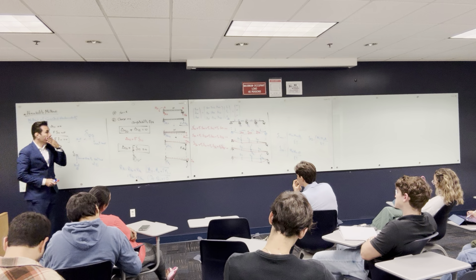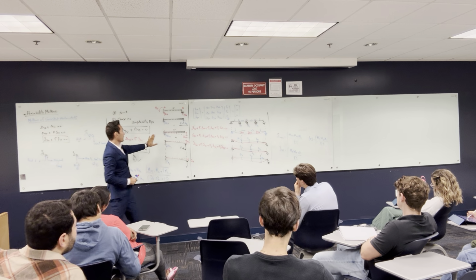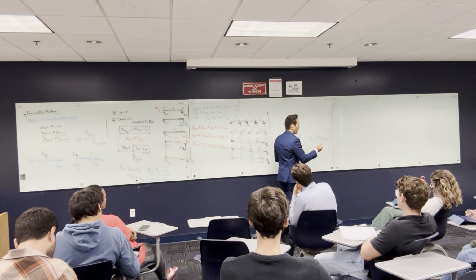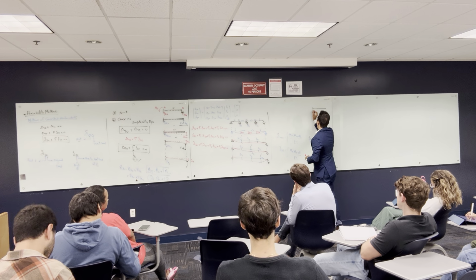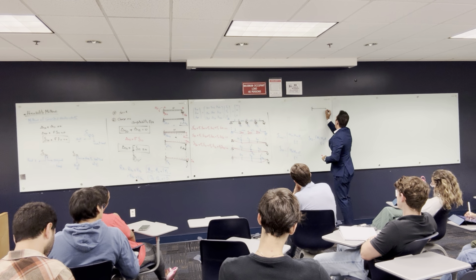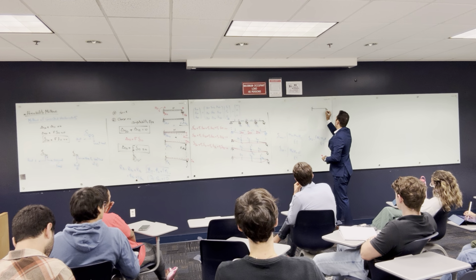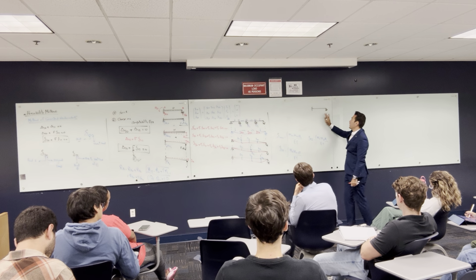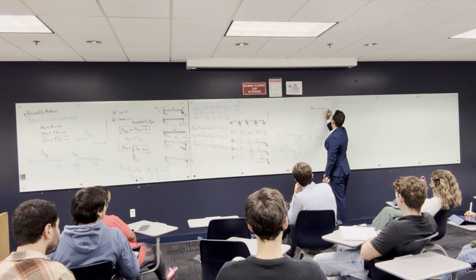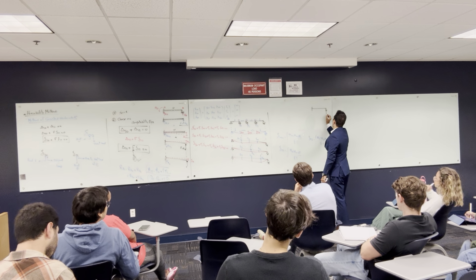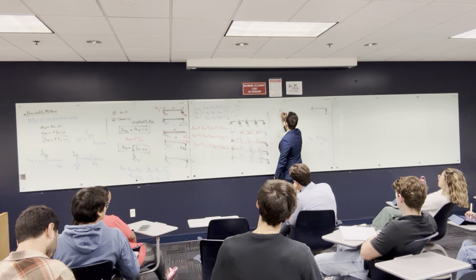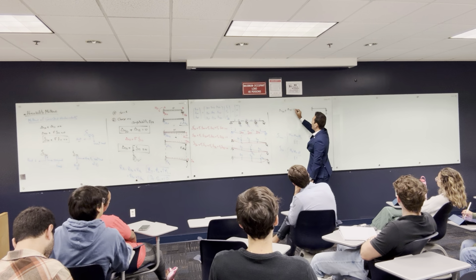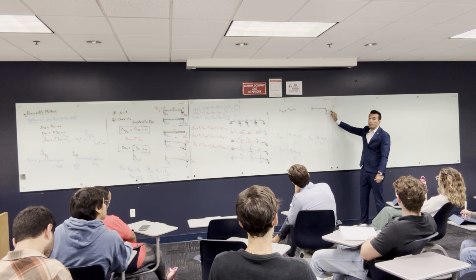All right, I wanna tell you something that is a little bit tricky. Can you see this? What if this problem, rather than having a support like this, what is the value of the delta here? 0. What if I put a spring? Before, the compatibility equation was delta 1O plus delta 1 equal to 0. In this one, it doesn't equal 0. Why? Because there's a deformation here.